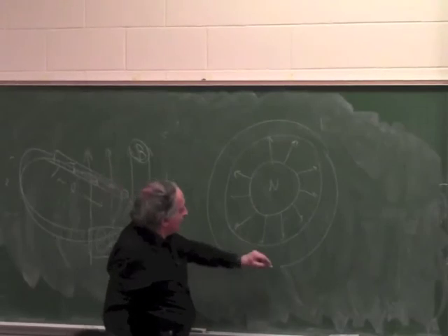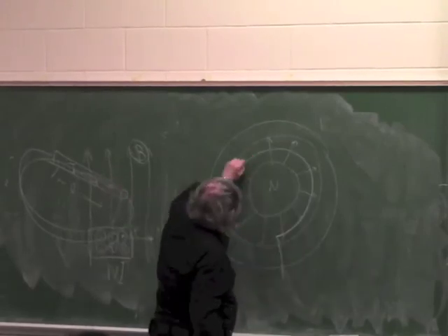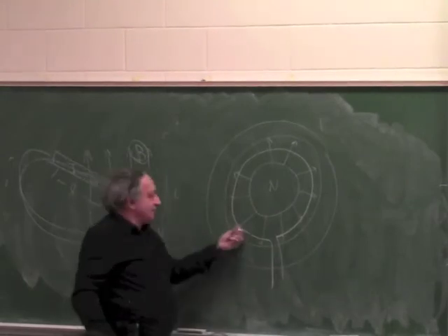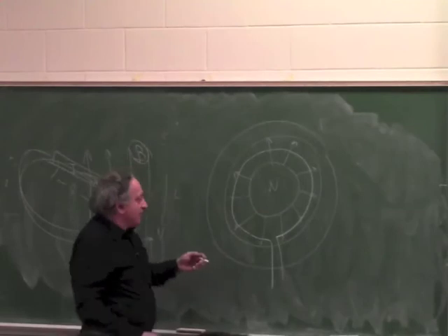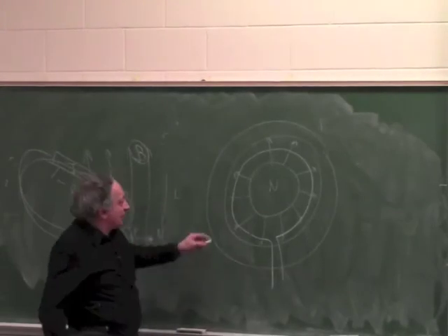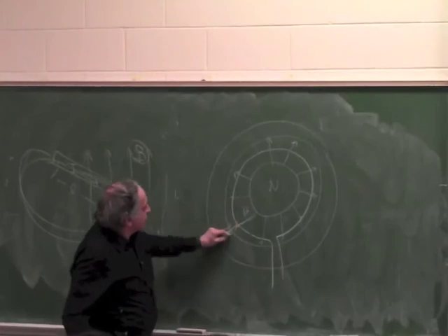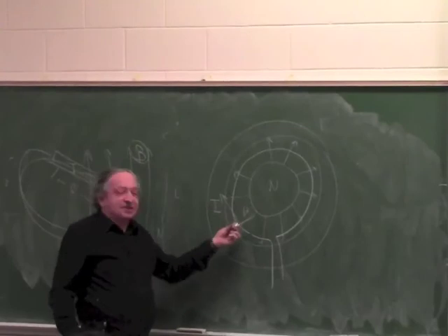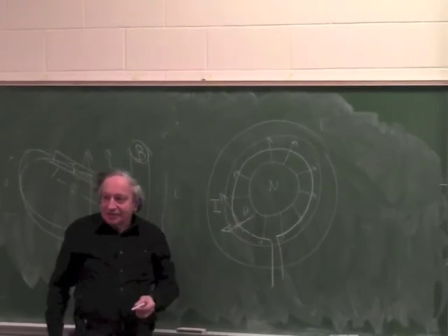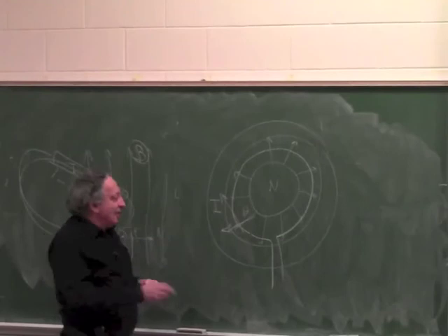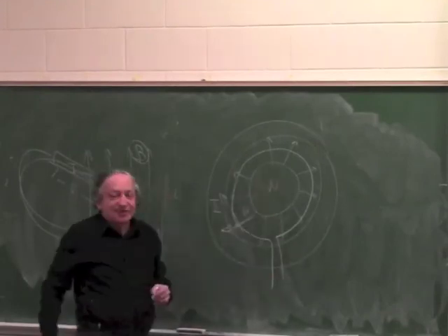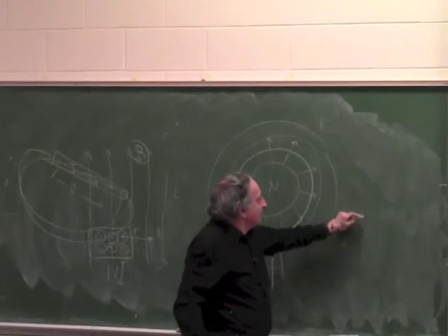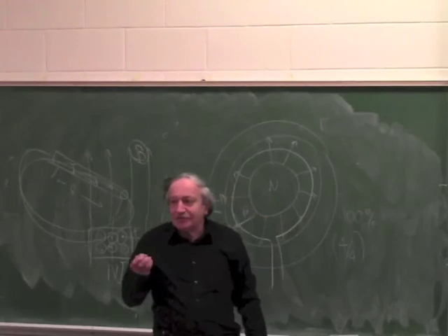Okay, now if I put a loop of wire in the radial field, every bit of wire will have a force on it pushing in this direction. Because remember the three vectors are perpendicular, so I have B in this direction, I have I in this direction, so BLI will come out like this, or like this, depending on the direction of the current. So if I make the field radial, every piece of copper creates force, and then I get 4 out of 4. It's not 4 anymore, but basically I get 100%. 100% of the mass creates force.